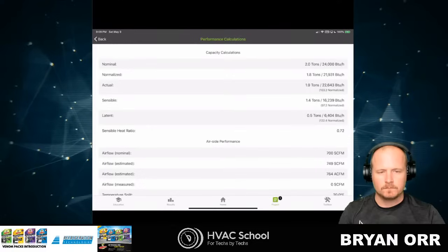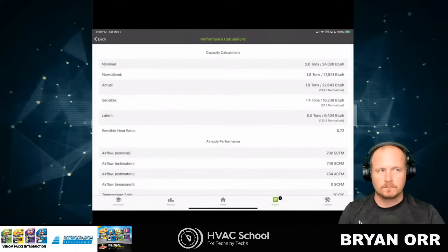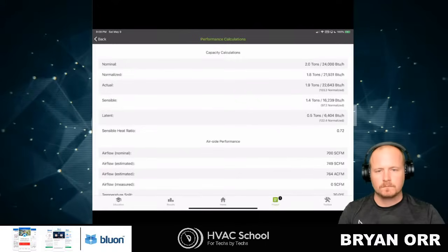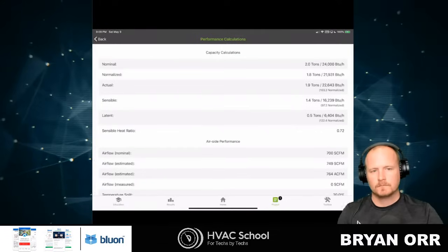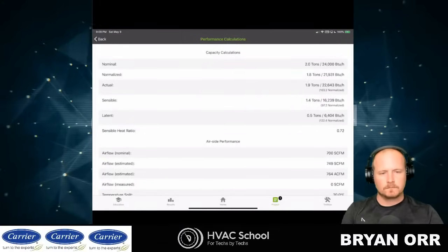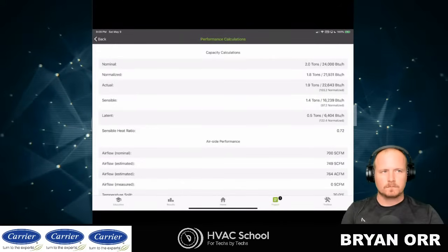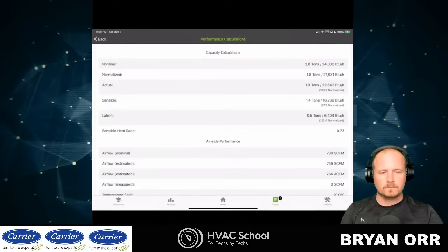So if we had it set up for a 0.75 sensible split, in other words, we engineered it so that 75% of the energy was going to cooling the home and 25% was reserved for dehumidification, you could have a unit in Arizona that's doing 100% of its sensible cooling, but the reserved capacity for dehumidification is doing nothing, and that system is running perfectly.